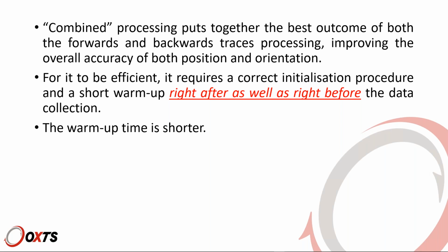So basically, it means that you will have to include a short warm up right after as well as right before your data collection, and you will have to finish your data collection with a straight line, which will be the first thing that the backwards trace sees and uses for its initialization. Either that, or you stand still for a couple of minutes in an open sky spot so the backwards trace can initialize statically. So keep this in mind.